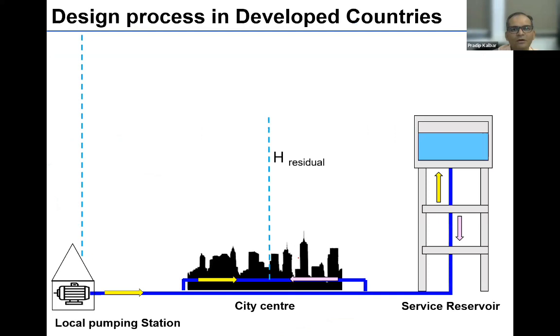Many people talk about pump distribution, using pump distribution for the cities, by looking at the Western countries or developed countries model. But one point we're forgetting is that we can use this system when we can control the demand, or the demands are defined. In cities like ours in India and developing countries, demand is very unpredictable. So typically what is expected is that average flow will come from this, and during the peak time, water will be coming down from this floating reservoir.